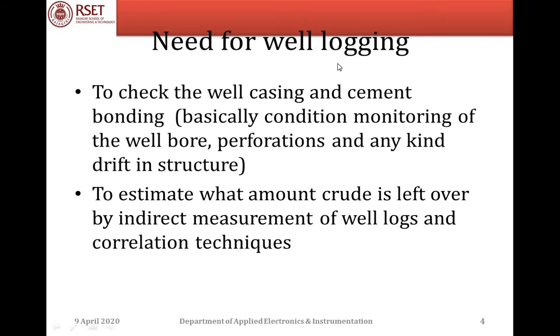Need for well logging. There are mainly two needs for doing the well logging operation. The first is to check the well casing and cement bond logs. Basically, it is the condition monitoring of the well bore perforations and any kind of drift in the pipeline structure or well bore structures. The second need is to estimate what amount of crude is left over by indirect measurement of well logs and correlation techniques. We will come to correlation techniques in the coming slides.